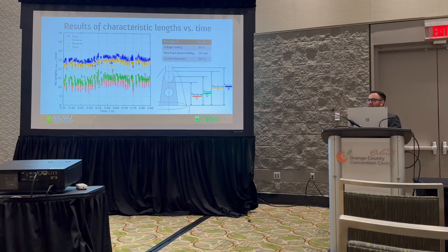So if you were to take a sample, for instance, a still image, and I say, okay, well, the top of the molten consumable, the arc length at that point is right around here would be 12 millimeters or just above 12. But if I measure over here, now I'm above 13. So it's definitely important to get a good amount of data to take an average so that you can obtain a representative value. So now if I zoom into just a few droplet cycles to see what actually happens,